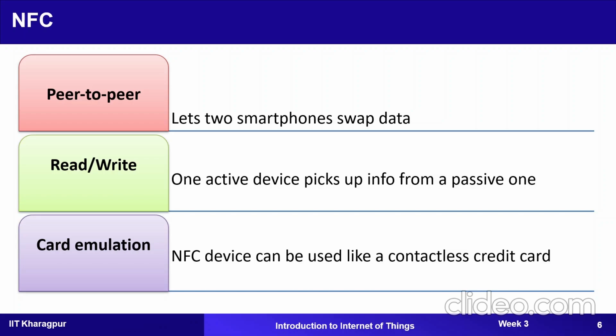There is no direct connection between the slaves. Two slaves cannot communicate with each other directly; they interact with the master. All the connections are either master to slave or slave to master. Slaves are allowed to transmit once they have been polled by the master. The master polls all the nodes connected to it to check whether they want to send data or not. If they want to, then only after the polling can they send the data.